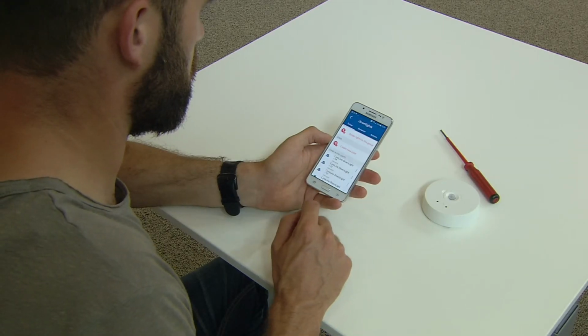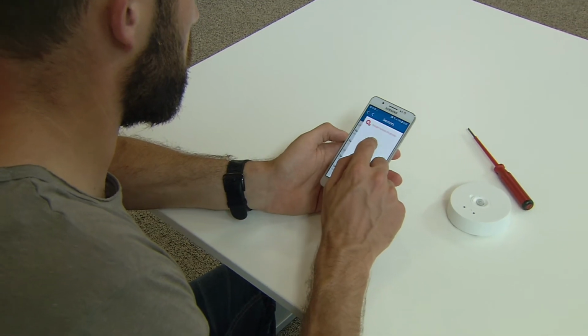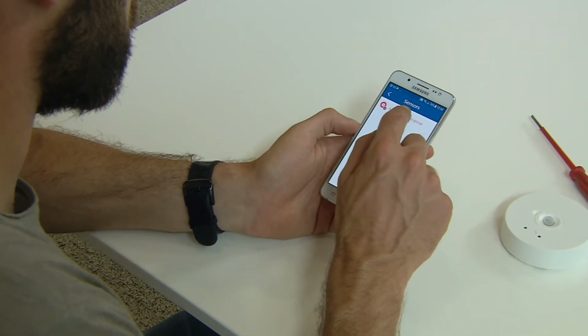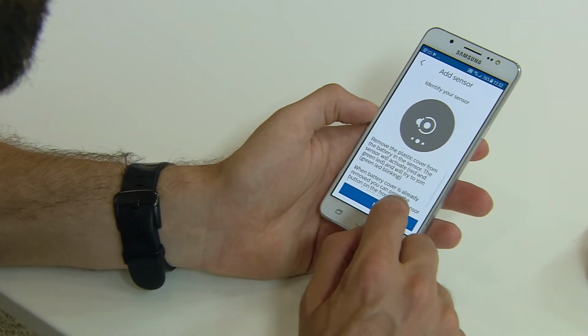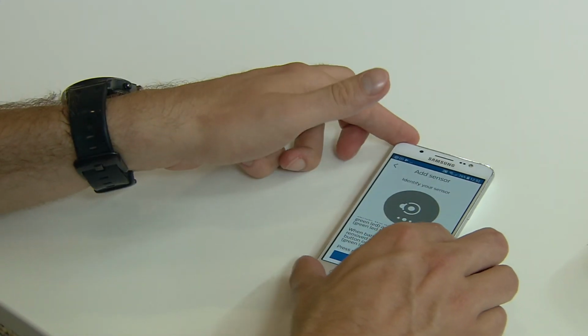Now we are going to add a control to the downlights group. Click Behavior and then choose Sensor this time. Click on Assign Sensor to Group, and you will now see clear instructions on how to progress.